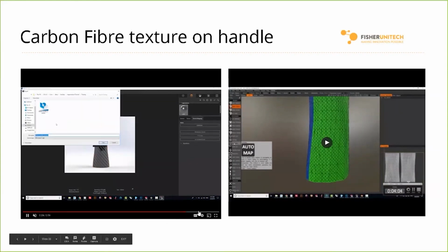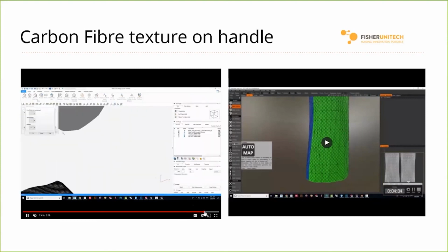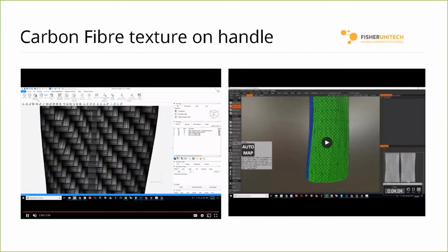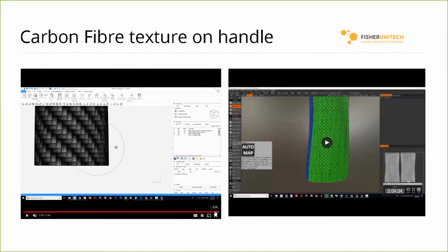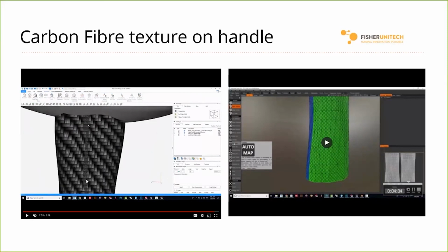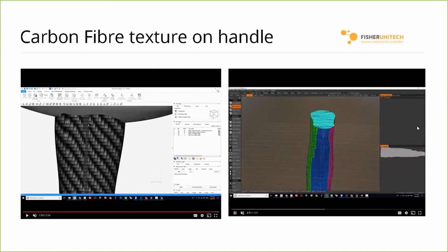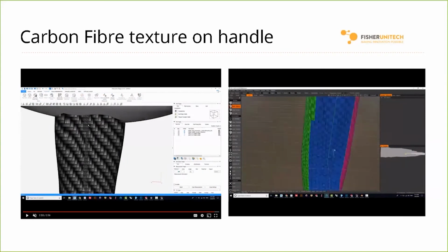So then I export it as an OBJ or a VRML. I bring it back into the program that I'm using for checking this. You could use GrabCAD Print as a way for checking your VRMLs if you don't have a tool like this. So you can see on the back of the object, I do have this seam. That's going to happen in most scenarios. But if you want to explicitly choose your seam, you can use a program like 3D Coat. So 3D Coat is a low-cost solution for doing explicit UV mapping.